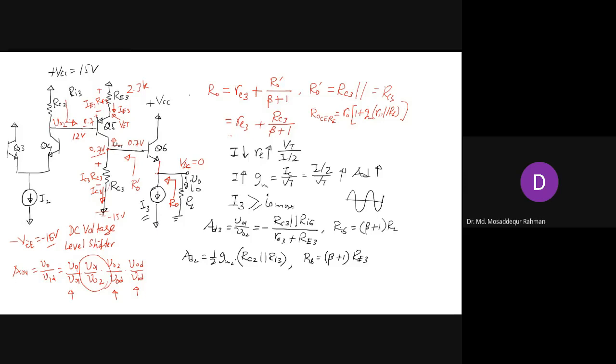If we consider this an AC signal current, it has a minimum value and a maximum value, right? So that is I naught max. So the I3 that you choose here has to be at least equal to or greater than I naught max. First you have to determine the maximum value of I naught max. That depends on the maximum value of the voltage that your amplifier will produce across the load.